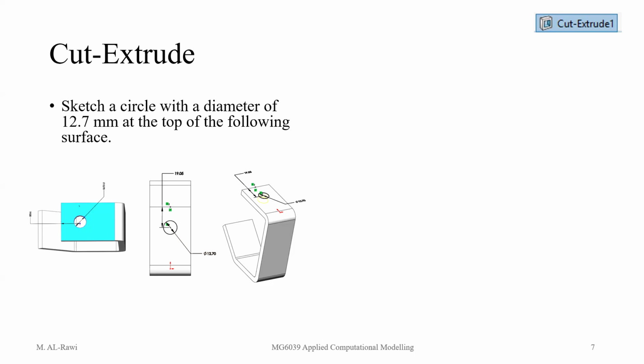So select dimensions, select the center, go to that line. You were just there. Why did we switch off? The center and that line, and then move. Make that 19.05. Because you drew a line and created a relationship, it doesn't accept it. So delete that line you drew. Now go smart dimension. Select the center and that one. What is telling me that you created a relationship here.